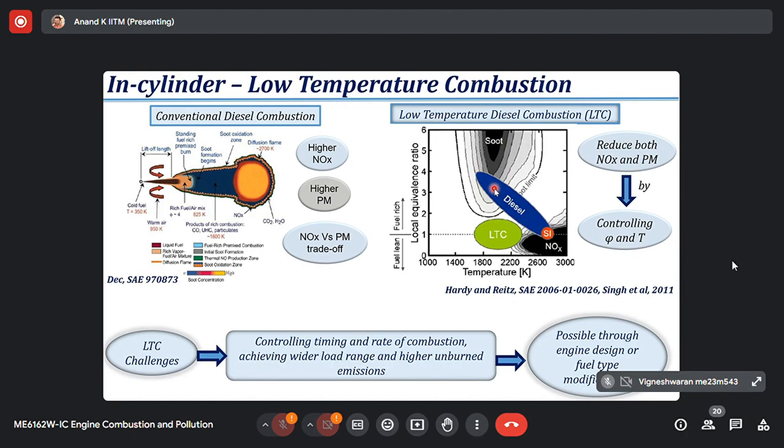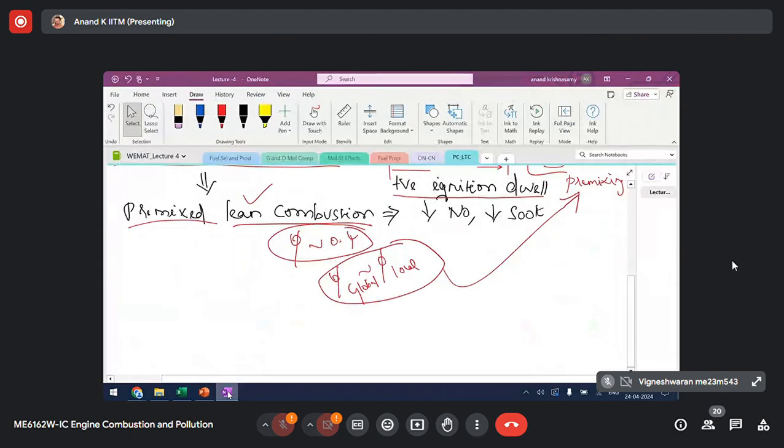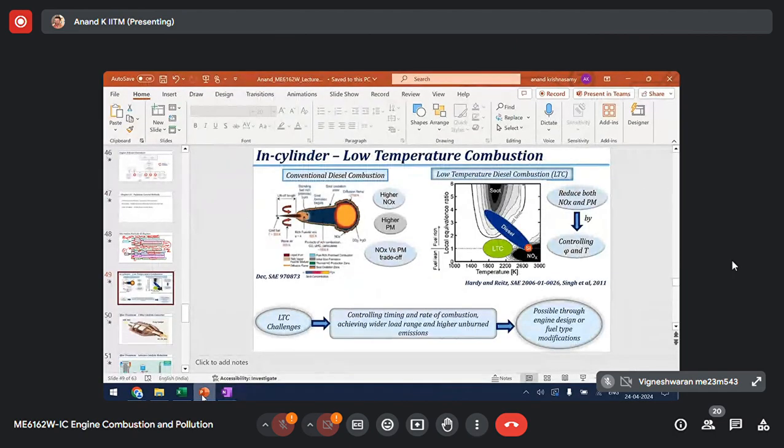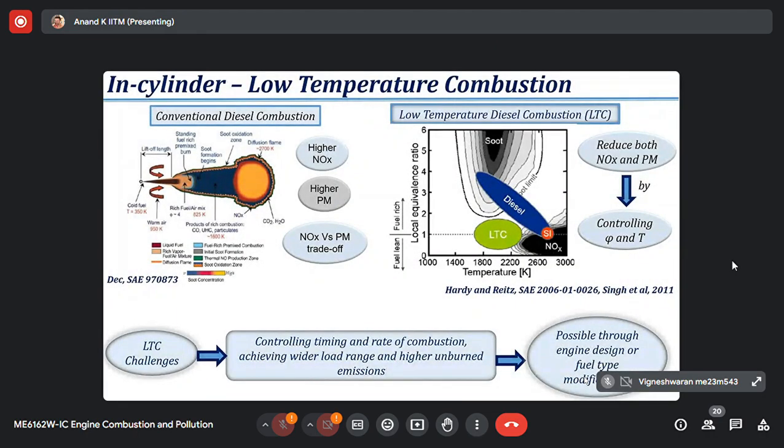Clear? Sir, here you are completely eliminating the undermixing phase, right, sir? Undermixing of the fuel. Yes. So the diffusion phase will not have any fuel injected in the combustion. You don't have a diffusion phase combustion. That is exactly what is happening here. In a conventional mode, due to negative ignition dwell, you have a diffusion phase combustion. Here you are eliminating diffusion phase combustion. You have only premix. Sir, in this combustion mode there's a dominant premix phase, right, sir? It's only premix phase combustion.